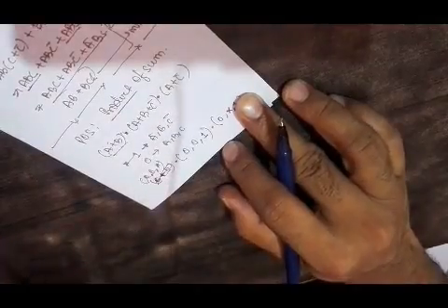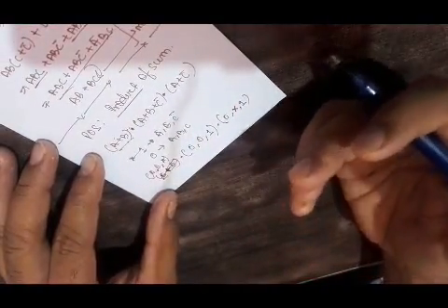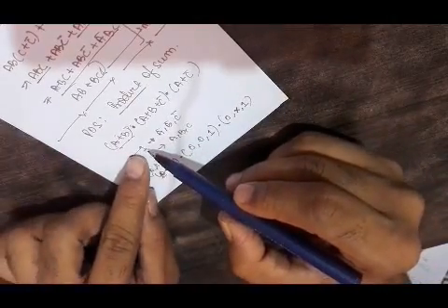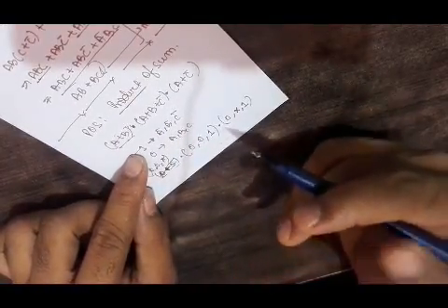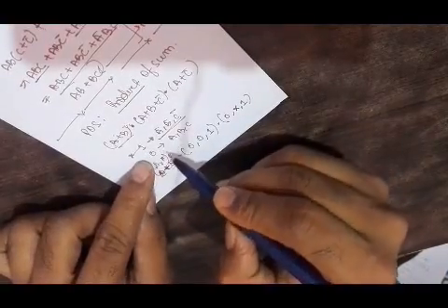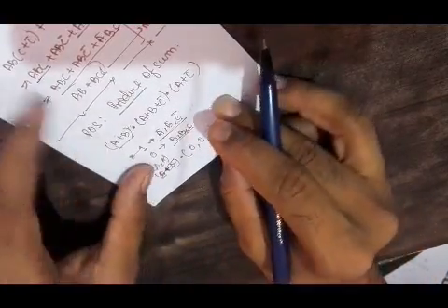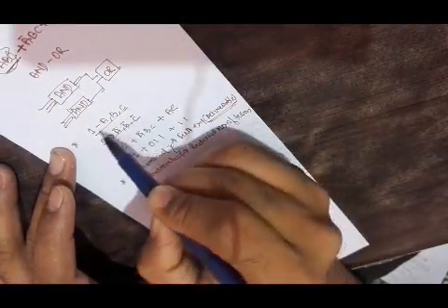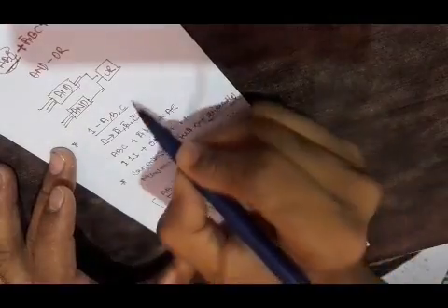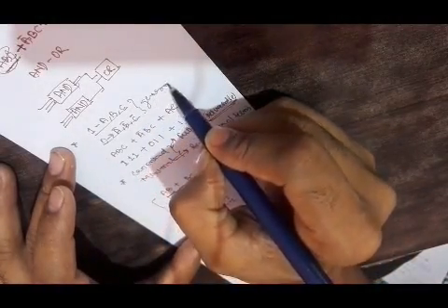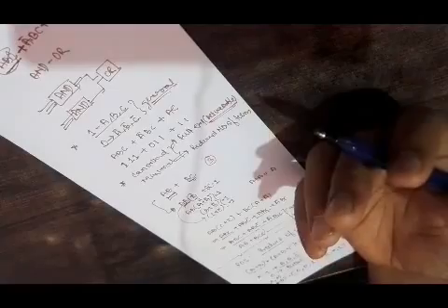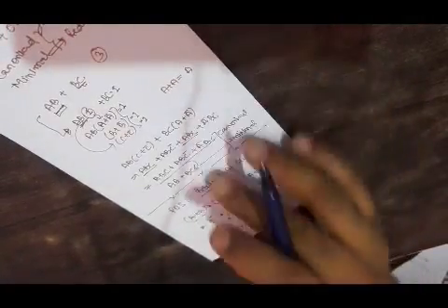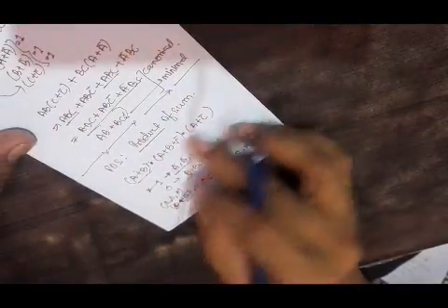So in canonical form, we're going to convert it into canonical and minimal form. But you have to keep in mind that 1 is a representation of the complement of A or complement of B or complement of C, and 0 is a representation of A, B, C. Whereas in sum of product, 1 is just A, B, C and 0 is its complement, which is the general trend. But in product of sum, we take 1 as the complement A bar, B bar, C bar and 0 as A, B, C. So product of sum is just the opposite of this, and you have to keep this in mind.